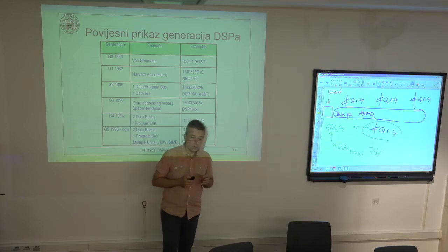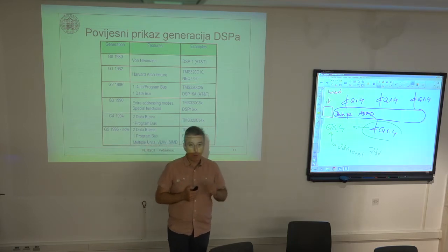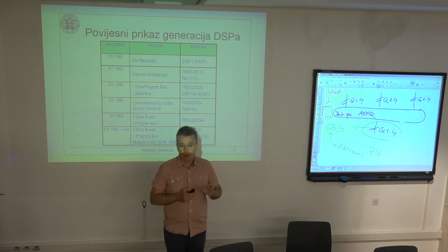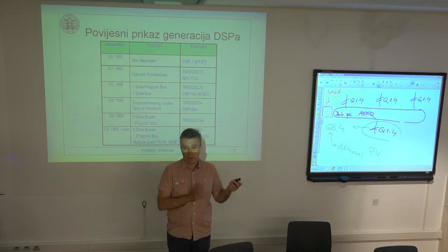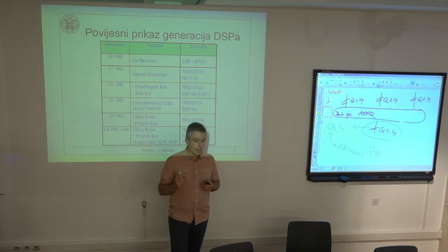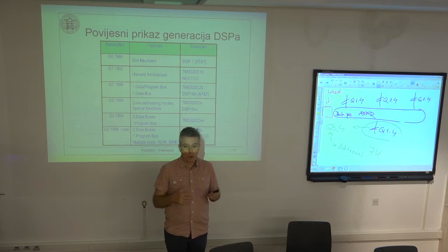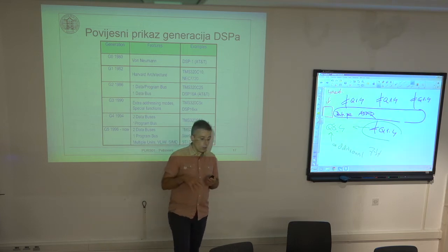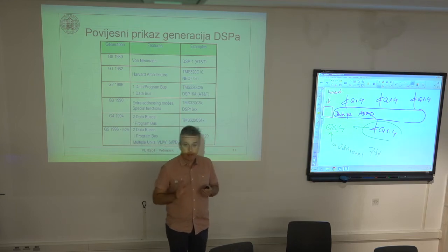But besides these 8 cores, they have 3 DSP cores, and in the case of Qualcomm chips these are called Hexagon DSP processors. These 3 cores can run simultaneously in parallel to the 8 cores of the main CPU, and each of these DSP cores can execute some of the real-time data processing tasks. For example, speech coding, decoding, video coding, decoding, or processing of the signals from the embedded sensors in your mobile phone. Because in a mobile phone, typically you have many sensors.